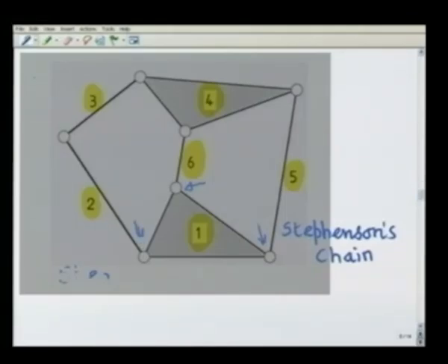And link number 4, the other ternary link, is also connected to 3 binary links, to link number 5 here, link number 6 here and link number 3 here. Thus, both these ternary links are topologically equivalent because both of them are connected to 3 binary links. However, so far as the binary links are concerned, there are 2 varieties, namely 5 and 6, and 2 and 3.